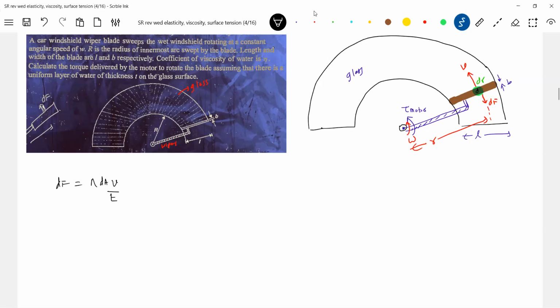If the wiper moves slowly, the viscous drag will be less, the scratches will be less. Suddenly, if you go for a higher speed, the viscous drag will be more, scratches will be more. So initially it should be at lower speed. Gradually, you have to increase speed. If you don't have this idea, ask your parent or any technician, or Google it, you'll come to know.